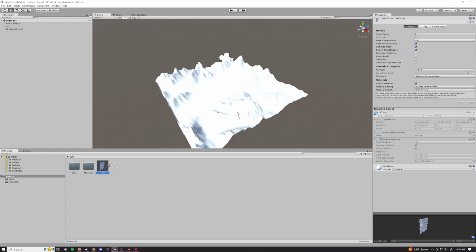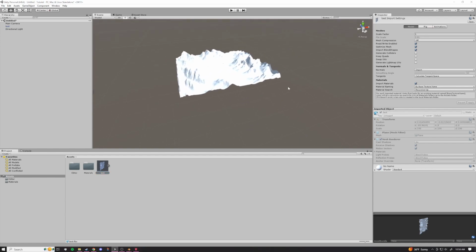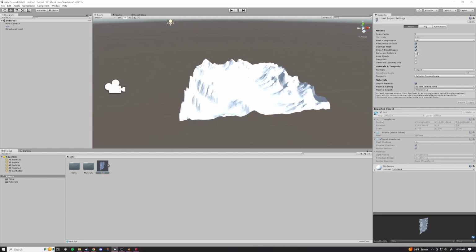And if you want to enable colliders when you export this mesh, now this mesh has no textures, obviously, but say we wanted to enable colliders, you would go over here and click Generate Colliders, press Apply, and now when you import this into Besiege, it's going to have colliders with it, instead of being completely passed through.